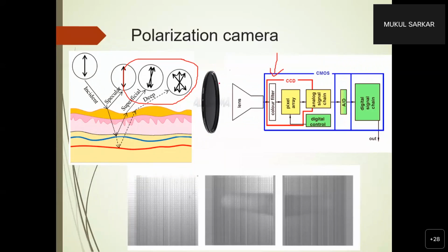a polarization filter, right? So you need this polarization filter, and if you have an unpolarized light incident onto it, then this unpolarized light passes through the polarizer, and one phase of polarized light is then incident, which is then converted into an intensity by the pixel array, right? And that's the only way of detecting phase information by a CMOS image sensor.